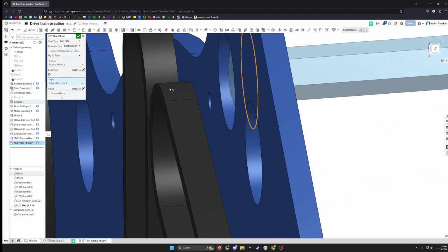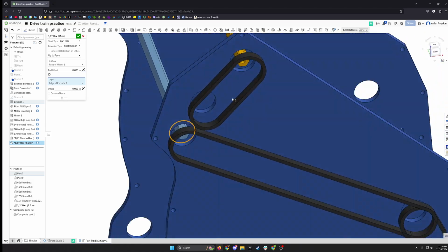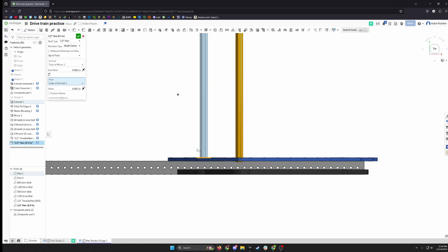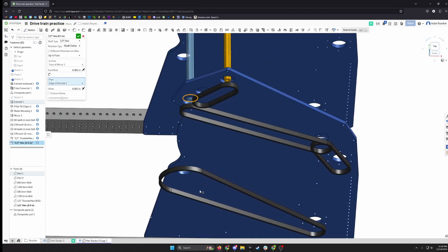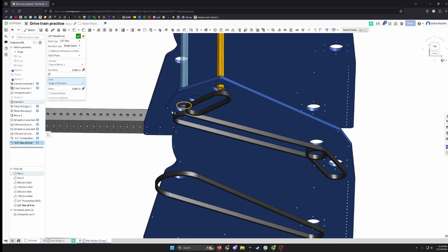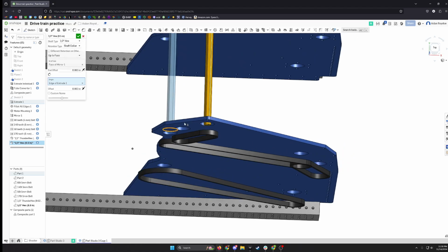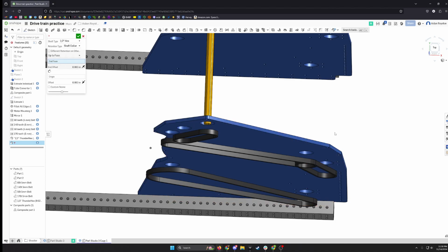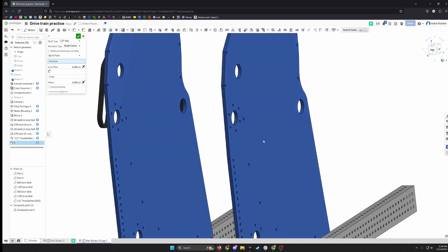And now, since we're going to have a pulley here, we need to have more offset this way. And each pulley is 1/2 inch wide. And so for each pulley that we're going to have on this shaft, we need to add 1/2 inch on top of our existing 16th inch offset for the bearing. And we can't just add 1/2 inch on this one, because we're going to have 2 pulleys on this shaft, which is going to be feeding over here. In fact, let's go ahead and just do that shaft first. It's going to be easier to explain.